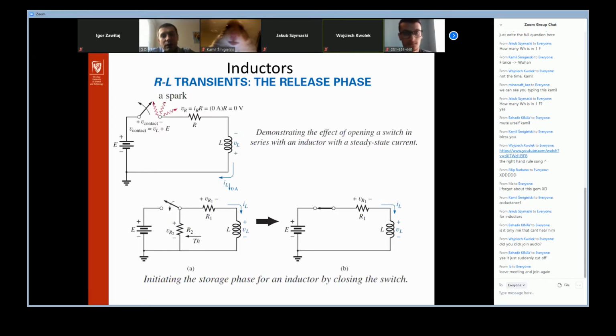So if we take it together, we've got the current, and sometimes it is a huge current, a few amperes, for example, and we've got a network of power lines which are giving us some nice inductance. That's why we can observe the sparks on the switches when we turn off.